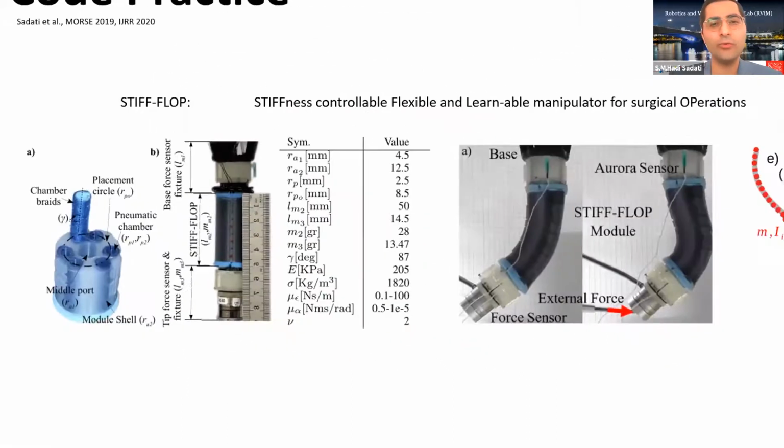That's why you need to do learning-based methods on top of theoretical models, or a PID implementation, to achieve high accuracy in controlling soft robots. There you can achieve 0.5 millimeter really easily with a PID implementation on top of the model.